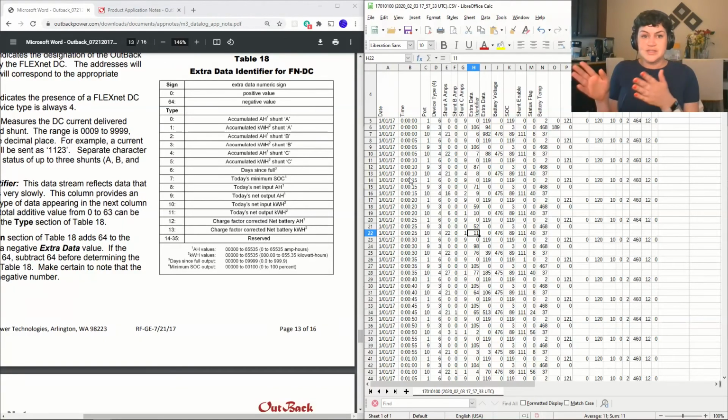And you can see that all here. You can see when the charge controller became silent. Oh, it became silent 2 volts before the inverter did. What is the inverter doing? You can see all the different modes and what the battery voltage is. What does the charge controller think the battery voltage is? What does the inverter think it is?